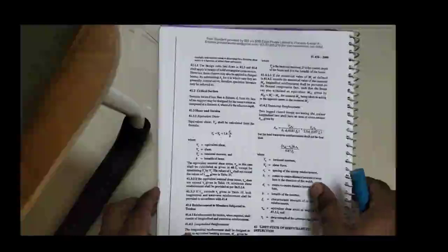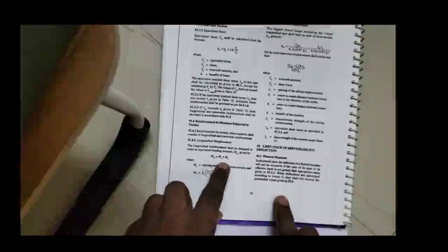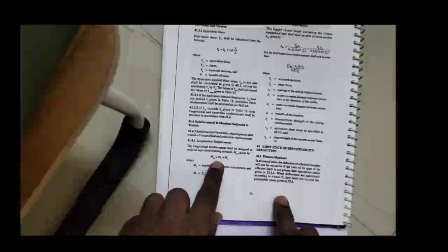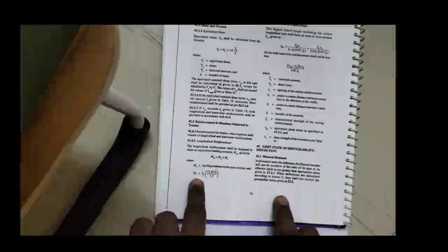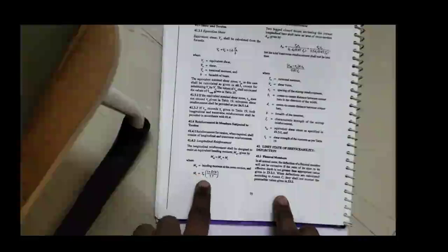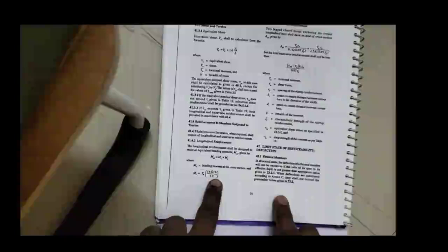If you are considering the moment, we have a formula called Mu1 equal to Mu plus Mt. Here Mu represents the moment which we calculate from the normal load acting on the structure. If it is a simply supported beam, then this Mu will be calculated by using the formula W L square by 8. Mt will be calculated by the formula Mt equal to Tu, the torsional moment which will be given in our problem, into 1 plus D by b, divided by 1.7. So this formula will be used to calculate the torsional moment.